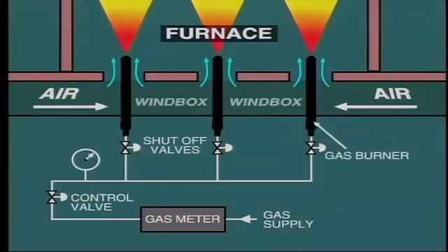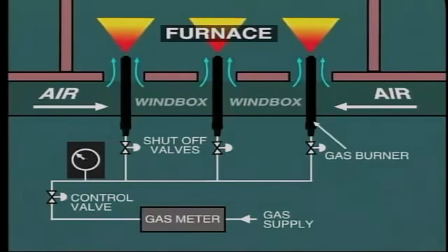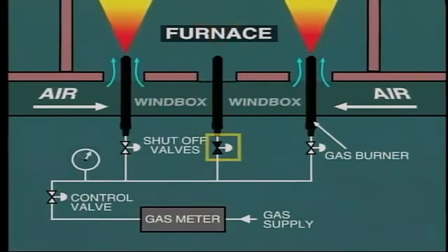Control of heat input to the natural gas boiler is similar to oil firing. That is, the flow of fuel to the burners can be adjusted by control of the fuel supply valve, at least over a certain pressure range. However, if the fuel supply is allowed to fall too low, we may get unstable combustion. In this situation, it's necessary to shut down one or more burners completely, and so raise the supply pressure to the remaining in-service burners.